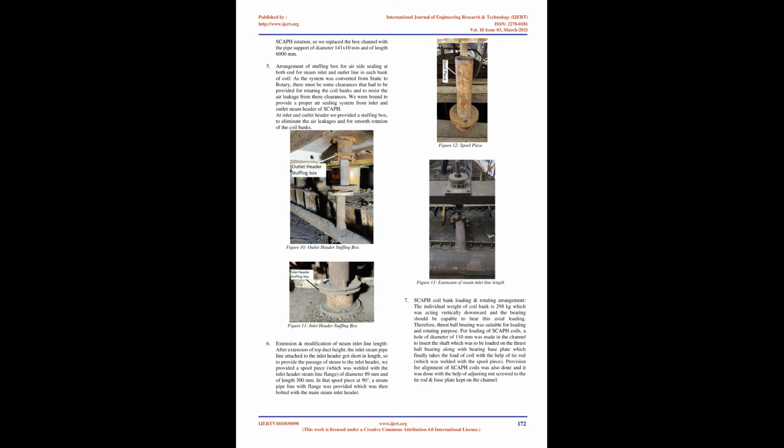One such condition is that the secondary air or combustion air temperature at APH outlet should be greater than 160 degrees C. Now, since ambient air at 30 degrees C passing through APH and gathering heat from the low temperature flue gas at unit startup will require more time to get heated up to 160 degrees C, by using SCAF the same activity becomes less time-taking. With the initiation of SCAF charging process we try to preheat the combustion air temperature from ambient temperature to at least 60-65 degrees C prior to sending it to APH for heat gain.